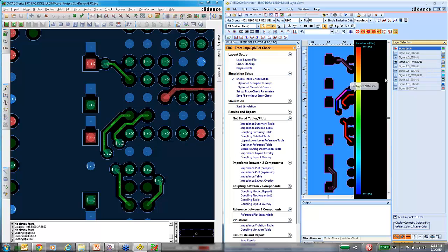the ground visibility or something here for the adjoining lower power ground plane. The top has 2 signal layers below it, and then a power ground plane. So that power ground actually has a voided area around that segment. So there's probably a pretty good indication of what's going on there. You can see that exact same trace over here. This is the area it's looking at. This is MD36 on that.